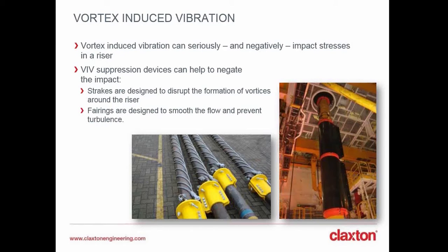Under these lock-in conditions, large resonant oscillations occur, and what they call lift forces are amplified due to the increase in vortex strength. So what this means is you'll have large responses in both directions, giving rise to oscillatory stresses. And if these stresses persist, then significant fatigue damage may occur.